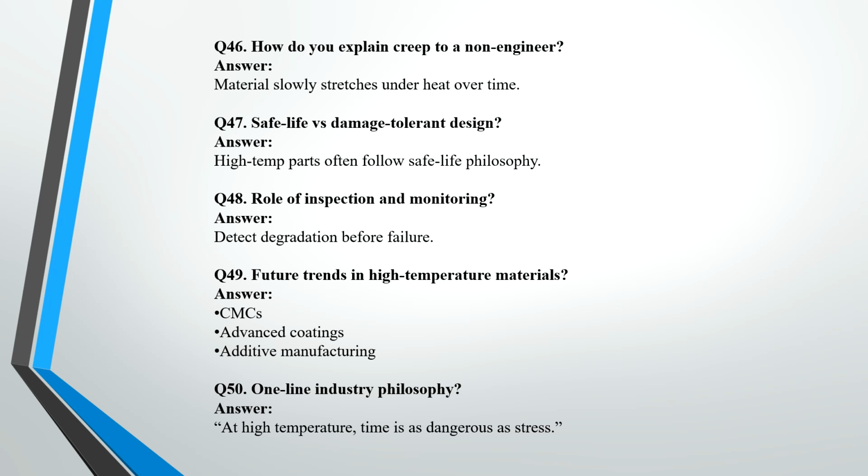If you say one line industry philosophy: at high temperature, time is as dangerous as stress. So time is very important, as in processes like creep. For example, if you take any material at constant stress and constant temperature, with respect to time, it actually deforms. So that's why at high temperature, time is very important, as dangerous as stress.